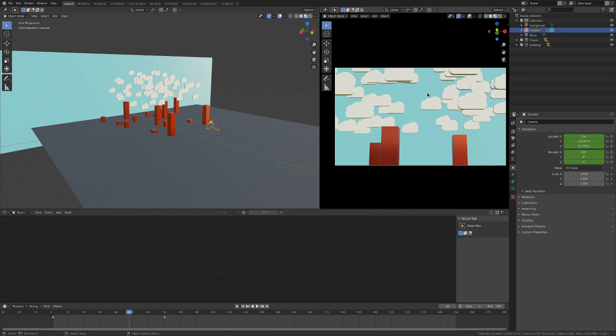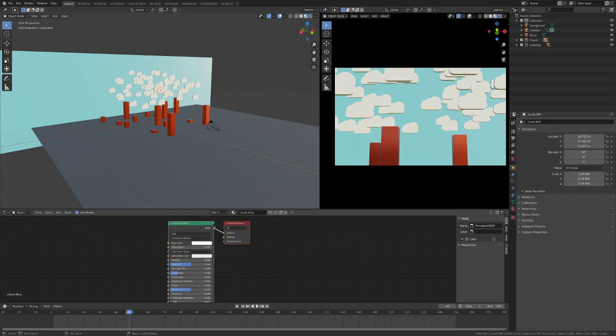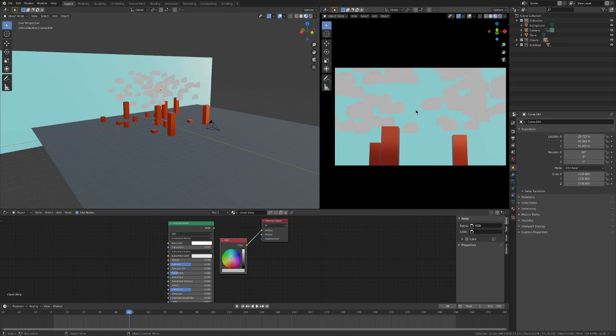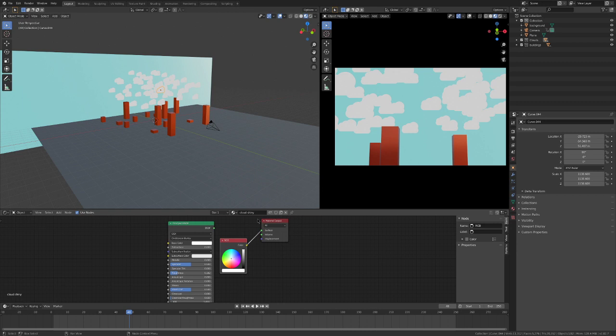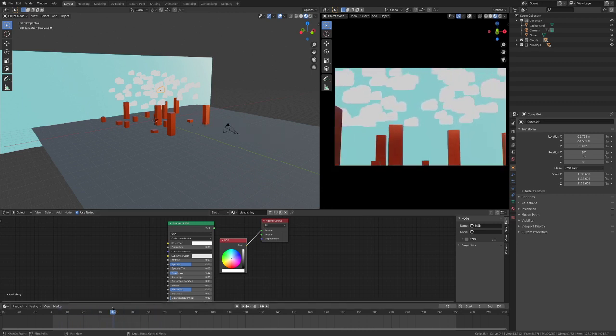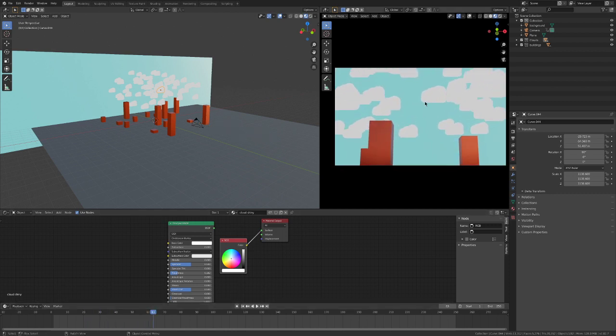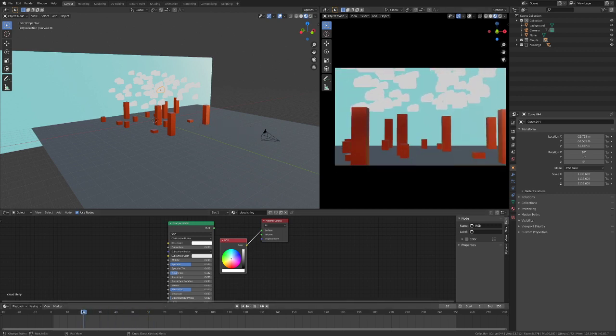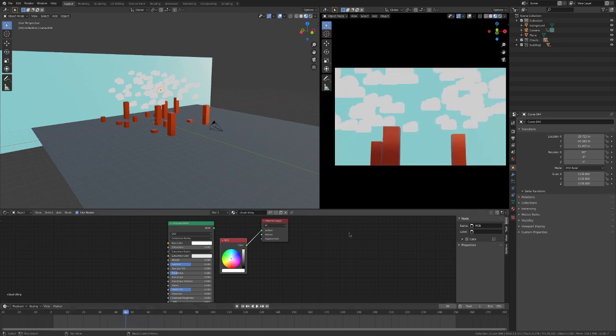I'll go quickly to show you a different effect here. Remember yesterday I showed you, and I'm going to do this again, that you can use RGB instead of a Principled shader, and you will remove any kind of depth. So we can still have it white, but you're removing any depth visualized. The object still has some depth, but it's just not visualized anymore, because all the sides are going to be the same without any kind of shading.